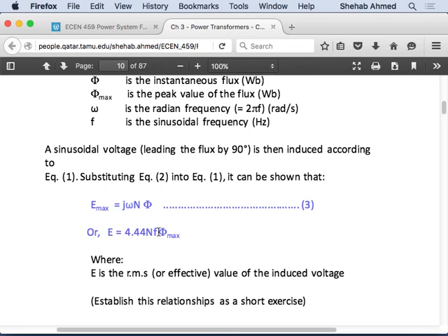Now, to sell this idea, you cannot just sell it as a replacement to a transformer. You have to sell it as a replacement to a transformer plus other nice benefits. You can also connect solar energy to it. Of course, you have power electronics; anytime you have power electronics, you can do whatever you want. Or you can also add storage. If I lose power on one side, you can still supply your loads because I have built-in storage.